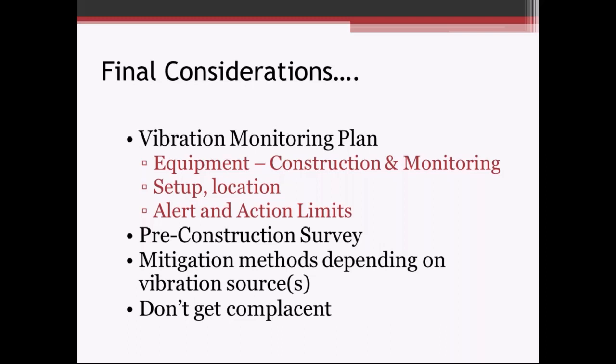You're going to record in histogram mode. What's your recording interval going to be? Maybe it's histogram combo mode. What are your alerts and action limits? When are those notifications going to go out? When are you going to start sounding the alarm, right? When do you need to turn down the energy on the hammer, or maybe not put as much downward force on those sheet piles as they're going in.